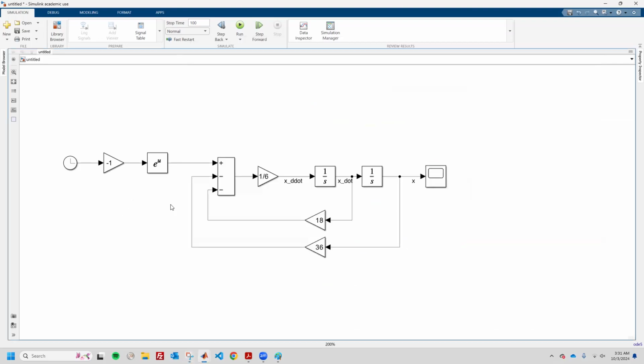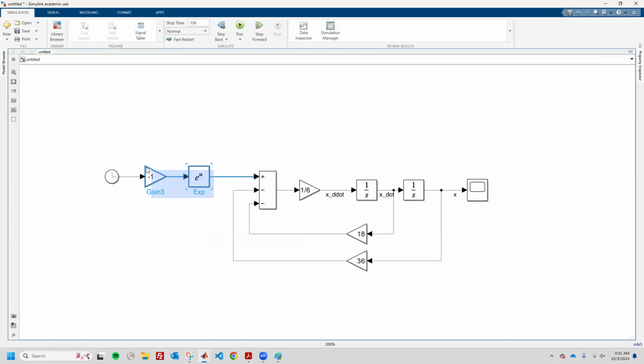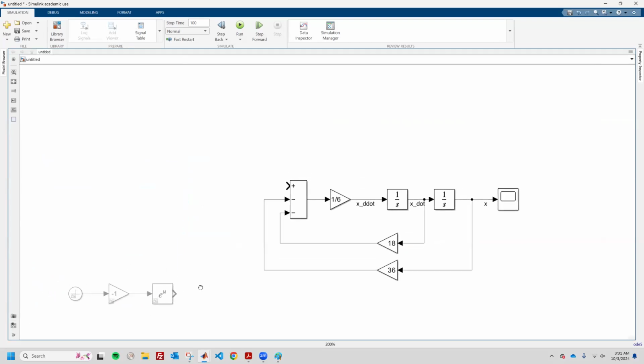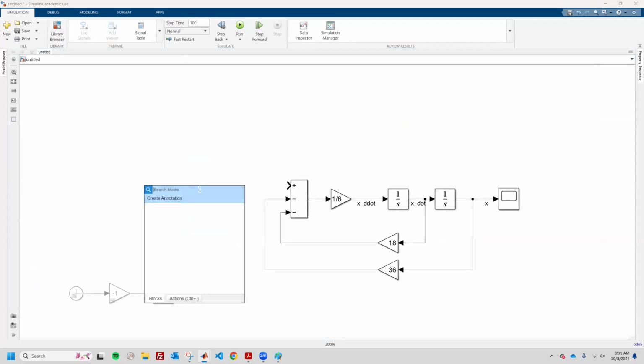So let's just do that. Another cool thing about Simulink is you can comment out Simulink blocks the same way that you comment out code. So let's say I'm not interested in this, so I can comment it out, move it aside, I can take out the signal. So now later on, if I want to move this in, I can just plug it in there and it's fine. Not the best practice, but useful for beginners. So I want to create that signal, right?